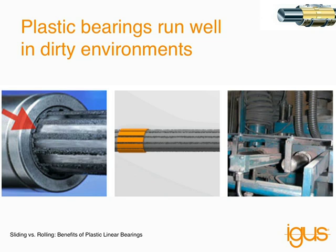We've kind of stated this a couple times in the webinar, but we get a lot of phone calls from customers who are using ball bearings. Maybe they're only lasting a month or 2 months, or sometimes even days, where the lubricants are being embedded with particulates and causing failure in the system. Plastic bearings don't have that problem because they're running dry. They work really well in dirty environments. They're able to wipe clean their shaft as they pull. They have dirt channels to enhance their performance, and a lot of problems can be solved by using these type of technologies.